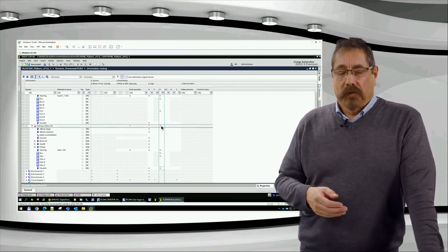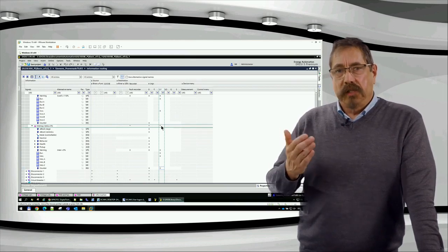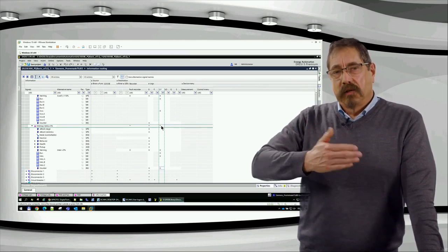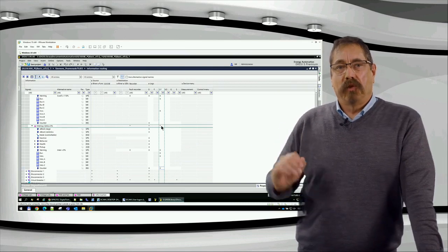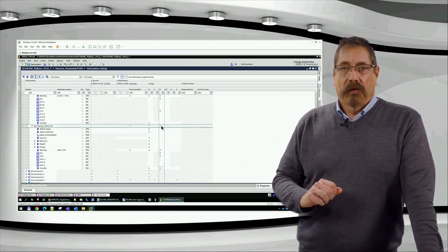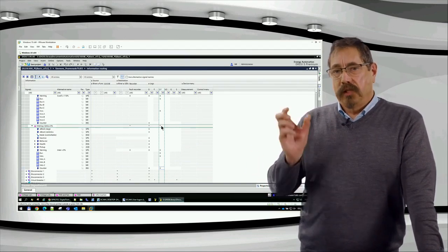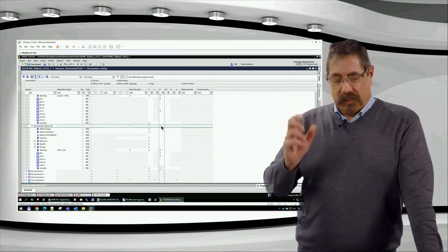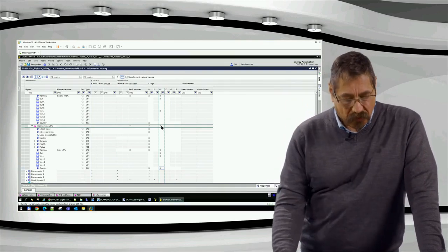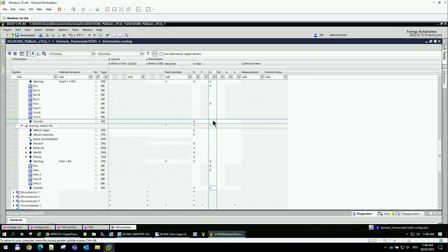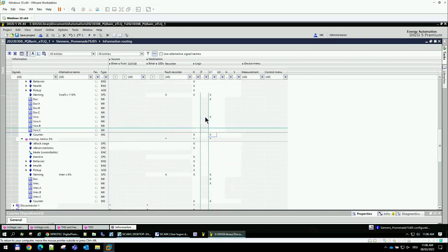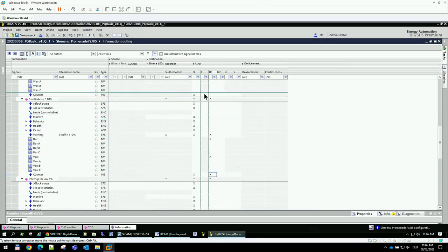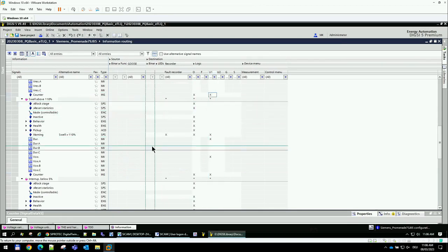Yeah, and have a clear statement. In this year, we had recognized 5 voltage dips, and the extreme value was this one, and the longest duration is that kind of seconds, milliseconds, or whatever. Okay, do not forget to add the counter information also to here, and also the counter for the voltage dip. Okay, good.